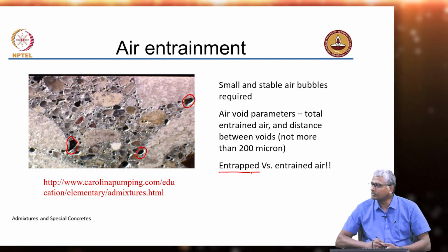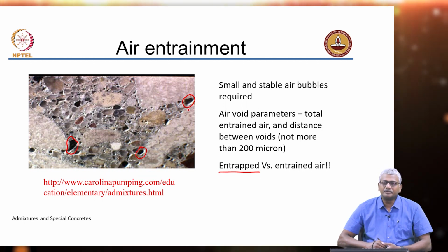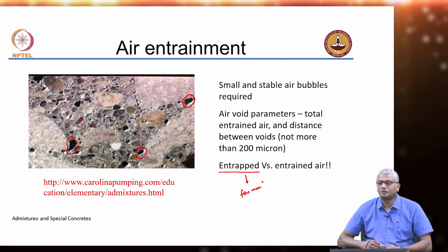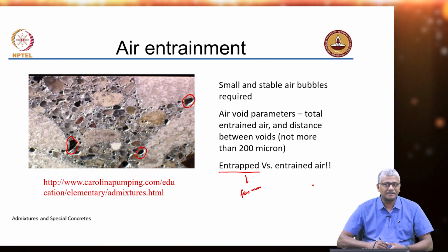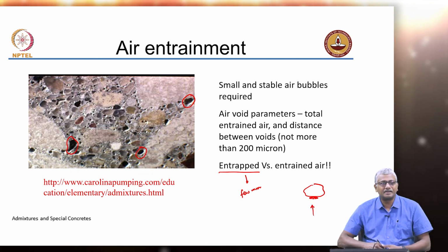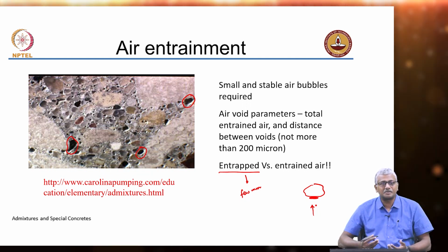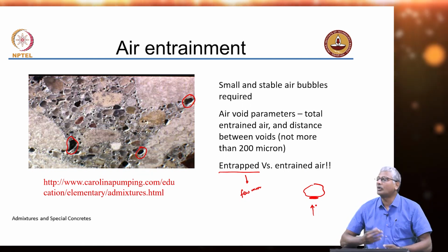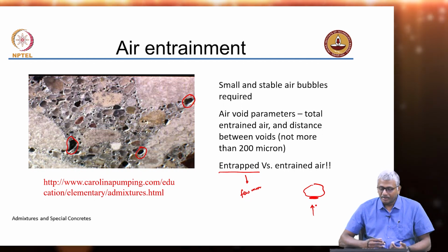Now, of course, in projects, people used to be happy to wait for years earlier. When we built our old monuments, those were built over years. The monuments did not come up in 3 months or 1 year or 2 years. People used to wait years for monuments to get constructed. As time passed on, we wanted to speedily construct and finish things fast. So, nowadays you have monuments and structures that are constructed in very little time. Because of this, the importance of C3S as a component of cement is only increasing, because C3S is the one which leads to early strength development.